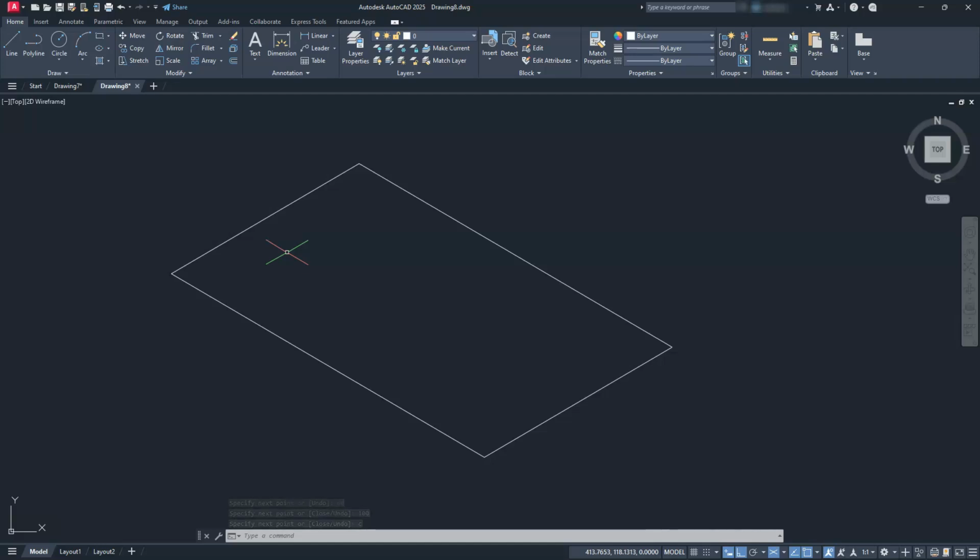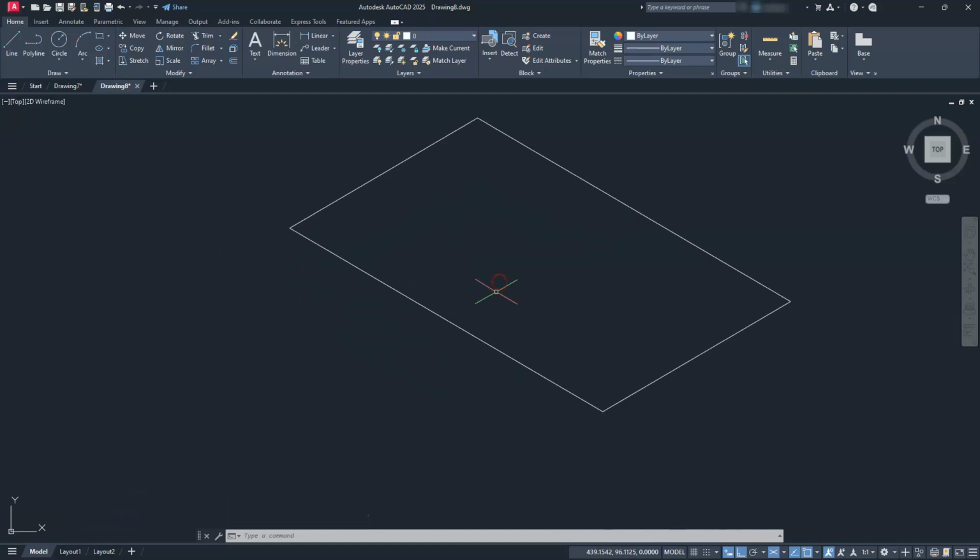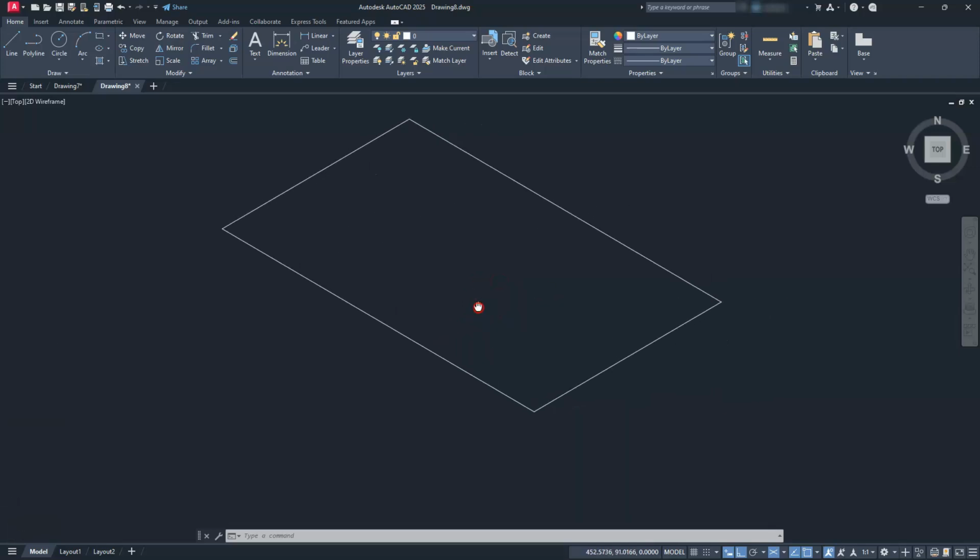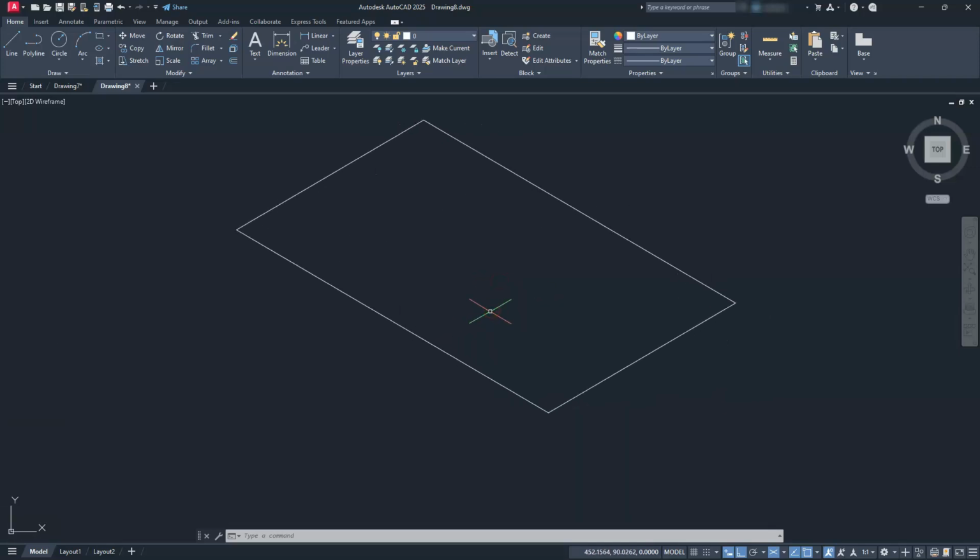And next, what I'm going to do from here is I'm going to start putting those fillets in here. Remember that we don't have the fillet command in this program, right? I have to create an ellipse. So EL, enter, then I, enter. I'm just going to click it here, and then the radius of our iso circle is going to be 30, right? So we have this shape, and I'm going to copy this to make two of them.